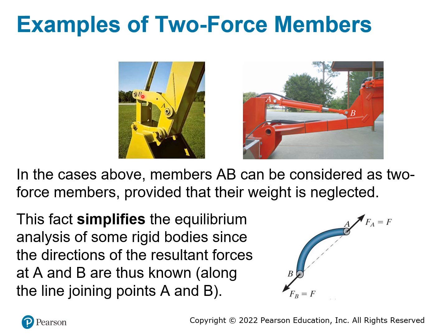However, if you look at this piece here, there's nothing else at the place where you apply force to this angled bracket, because you only apply force at point A and point B. Therefore, if you wanted to draw the force, the force will go along this line right here from A to B or B to A. It's going to be along this line.